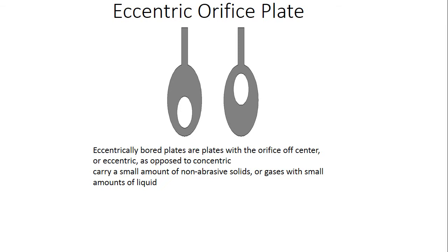Eccentric. This is the eccentric orifice where you see the bore is off the center, I mean it is eccentrically placed. So it can carry non-abrasive solids, where the solids can move, or gases with small amounts of liquid.